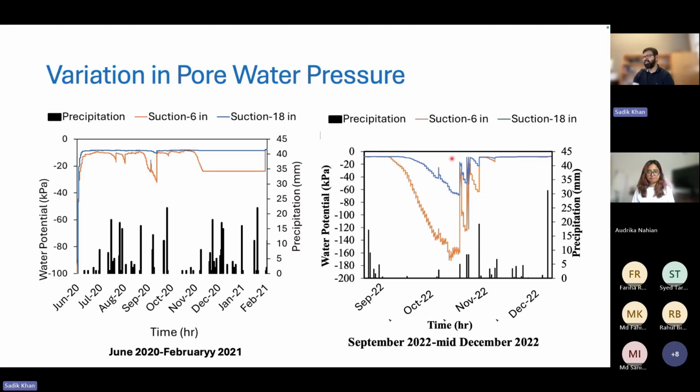With the suction variation, we can see that with the vetiver pulling off the moisture, the suction goes down. But you have to remember in Mississippi there is a lot of rain, and because there is a lot of rain, it's usually very superficial, so the moisture recharge becomes very quick in this area.